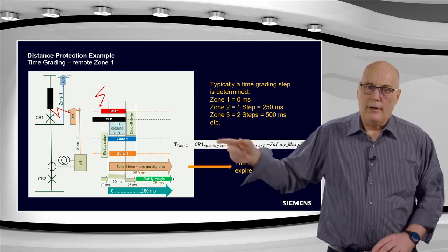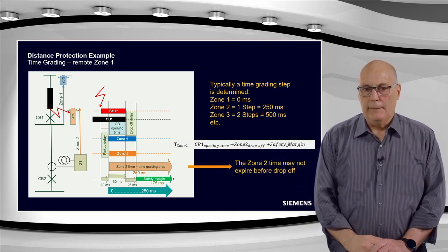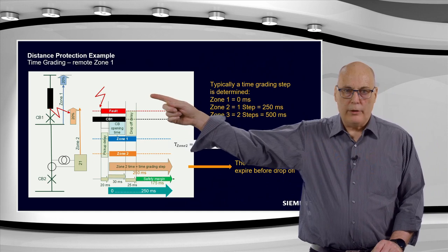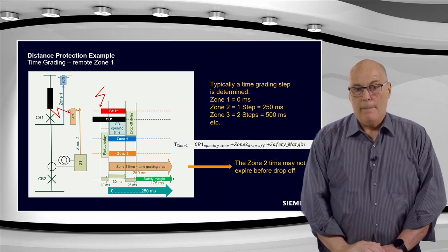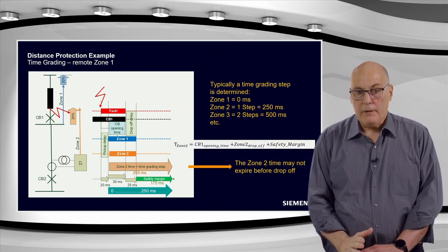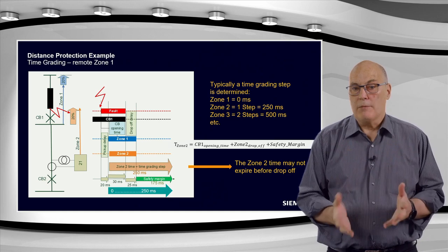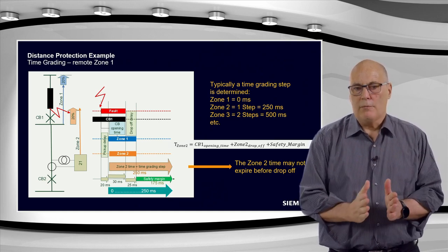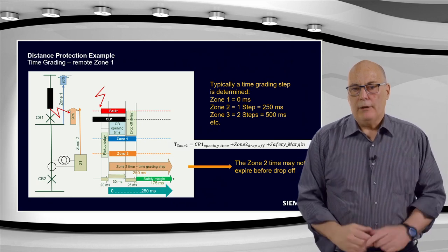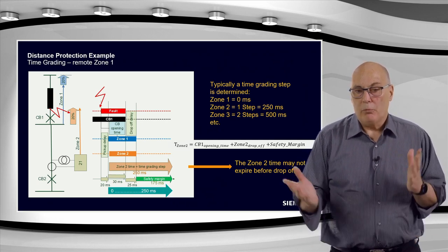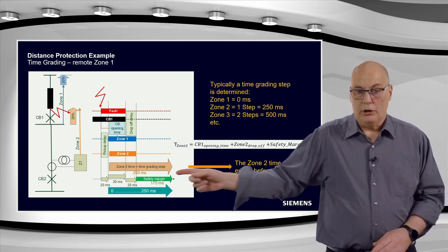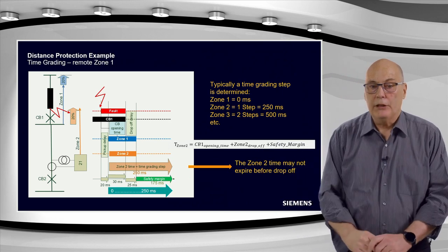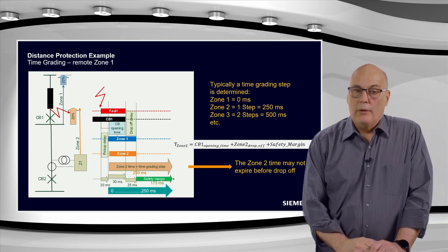Which brings us to this diagram where we can maybe explain that a little bit. So at the top you see the red arrow, that's time 0, the fault inception. There's a pickup delay. All the relays must measure. They will not instantaneously pick up when the fault appears. There's a small measuring delay. The measuring delay is very commonly 20 milliseconds or shorter. I just showed it as 20 milliseconds as an orientation over there. All relays will have something in that order.